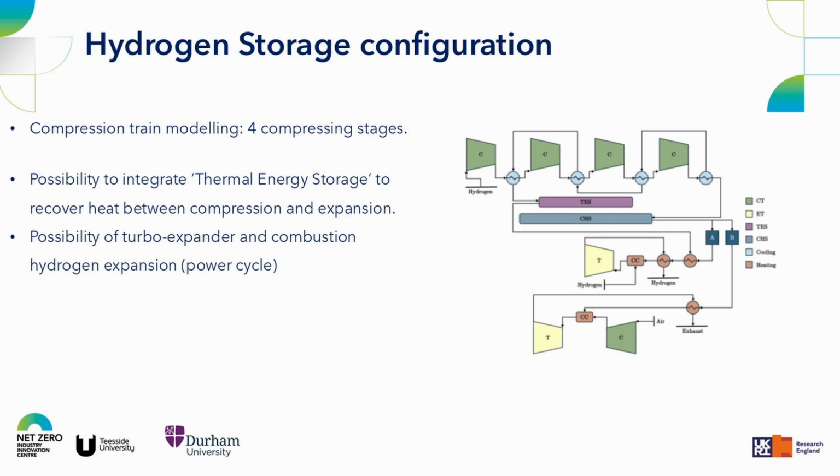As I mentioned, hydrogen is a very diffusive gas. So we are considering a 3% per hour leakage of hydrogen in the pipeline, which I think is normal, or we can consider an extreme condition of hydrogen leakage for this investigation.